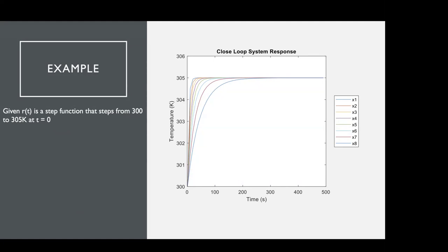How did you estimate the system error? Did you assume the steady state error was zero? I think she's being asked what happens if you turn that into a range, basically a dead band. How do you control within a range instead of a single value you're trying to hit? Because in reality, there's no way you can fix that thing.